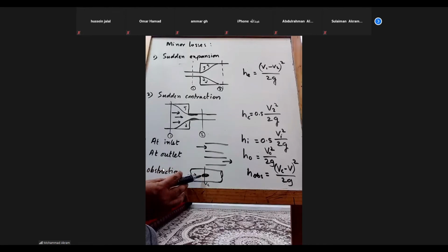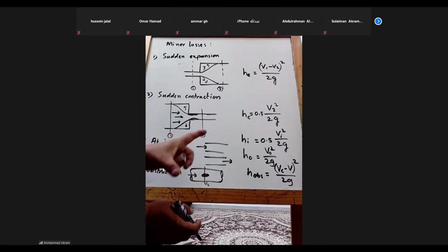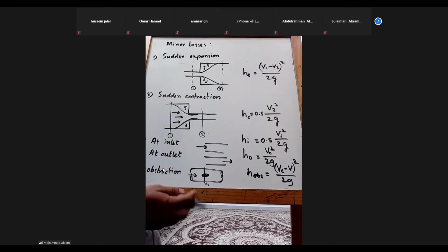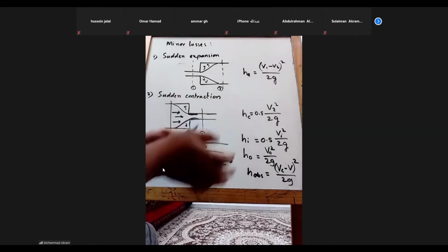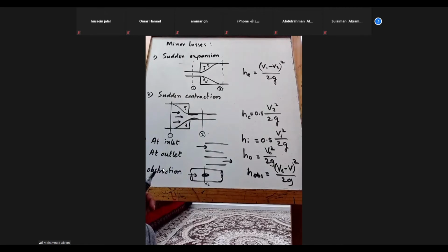If it is blocking a larger area, then the velocity will be higher, because if it blocks a large area, then the passage through which the flow is going will be smaller. So the area will be smaller, and it is like a nozzle. You might have tried keeping your thumb or finger in front of a water jet. So you will find the water from the other place will try to go at higher speed, right? Yes, right, doctor.